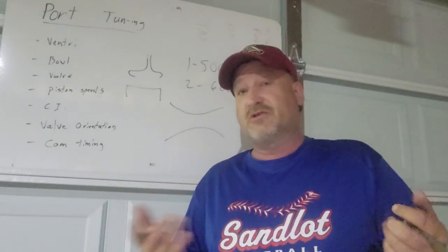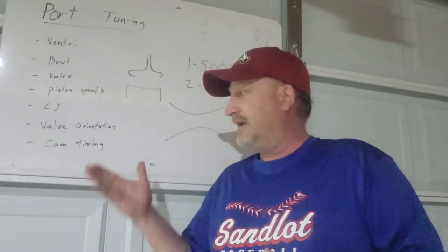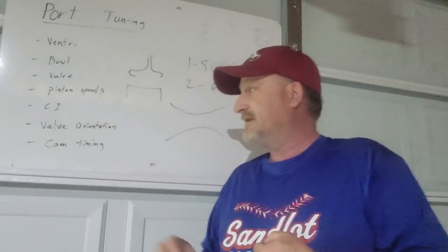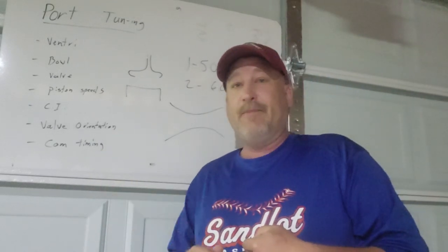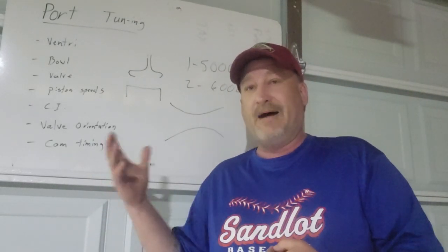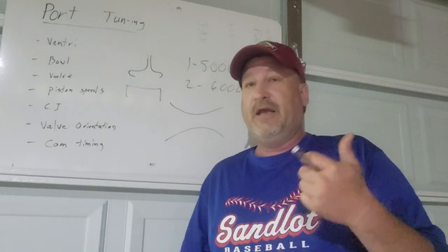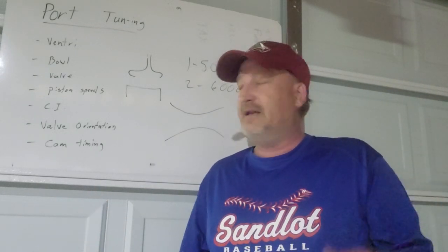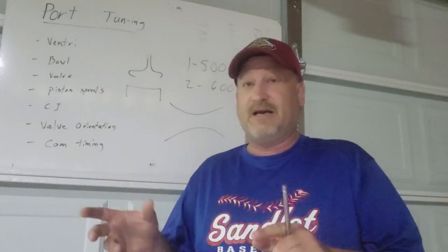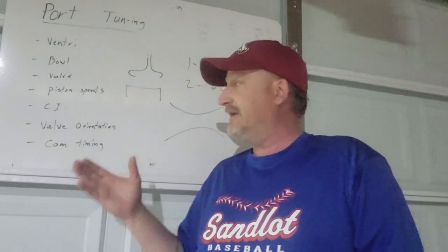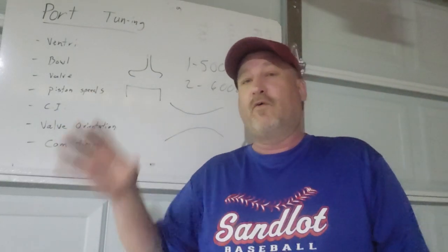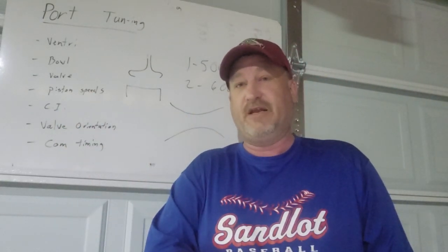Cam timing also alters that. Again, going back to the newer sport compact tuner type engines, the cam timing is done by the actual readings on the computer, monitoring the exhaust and the amount of fuel that's being injected in, and also altering the timing of the cams, whether it be one at a time or both simultaneously, to create the best port tuning for the RPM that the engine is running at.